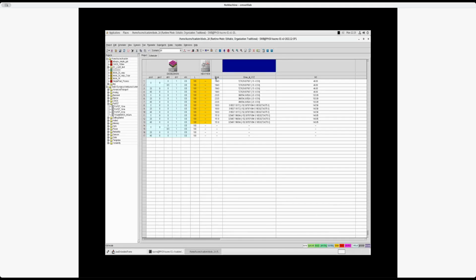For example, BVAK here is my breakdown value at K, which is extracted from our IV curve. There's a little math tool that we can use that can extract a breakdown from the IV curve of a diode. It calculates this breakdown and puts the calculated values in the grid there.